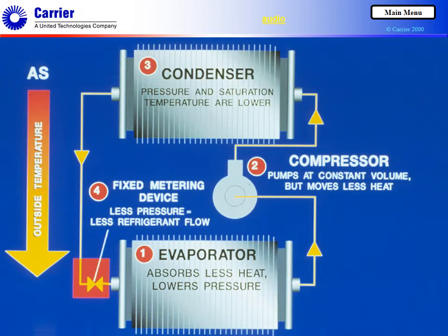In addition to this change, which was started at the evaporator, the condensing pressure usually is reduced further because of the lower outdoor temperatures that accompany a cooling load reduction on most small comfort jobs. This fact simply adds to the automatic downward compensation in capacity. Conversely, the reverse of the above steps is true as the cooling load increases.